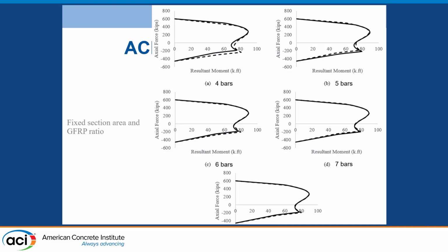Now, with 5 rebars and 4 rebars, you start to see some noticeable difference between them. Whether this is a significant difference or not is probably more of a question for those who have more practical experience than myself. If this difference is not really that significant in practice, then the ACI comment can basically be ignored, because obviously you cannot have less than 4 rebars in a circular section.